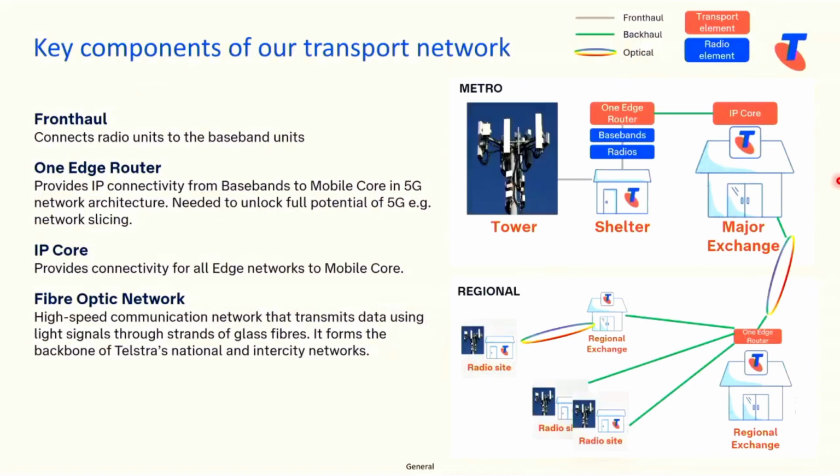Yeah. So we call, okay, front haul, that's what we call the connection from the baseband to the radio. And we can actually put those basebands, if we want to, together in a hotel. So you don't have to have them on site. You can have a baseband hotel and just run the front haul out to the radios. And then you don't really need a shelter there, but you do need to have some power and other things. And then there's backhaul. And backhaul is from the basebands back to the core. And that's our radio backhaul.